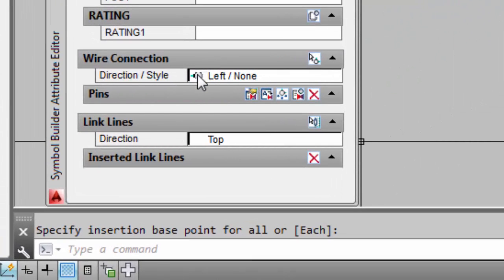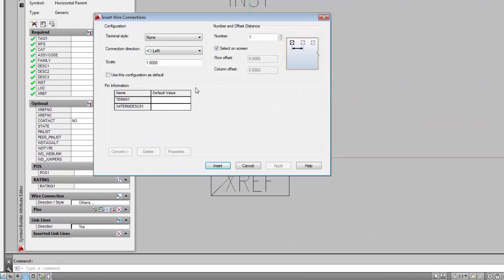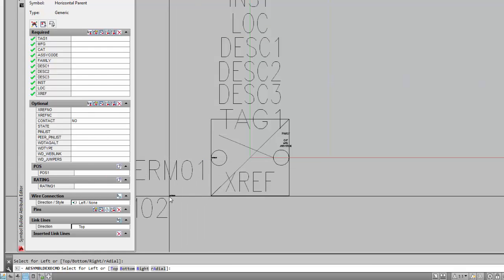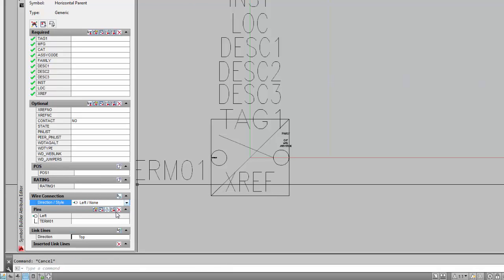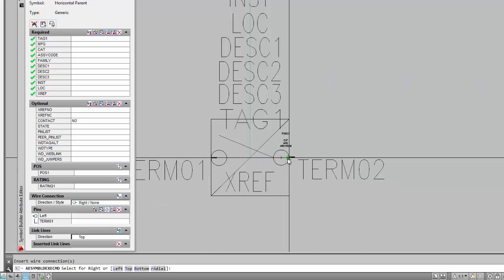Termination attributes serve multiple purposes. They provide all the information about each termination point a device needs and serve to tell AutoCAD Electrical how and where to break lines for wires. Termination attributes are also keyed to direction from which the wires flow. If you link to the left, you want a left terminal. If you link to the right, you need the right terminal attribute.